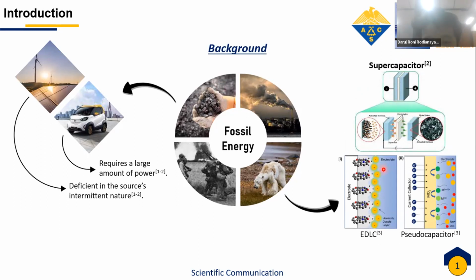Two types of supercapacitor based on their energy storage system are EDLC and pseudocapacitors. EDLC type supercapacitors work using the formed double layer, and pseudocapacitors use fast redox reactions to store energy. Therefore, a good electrode is needed.